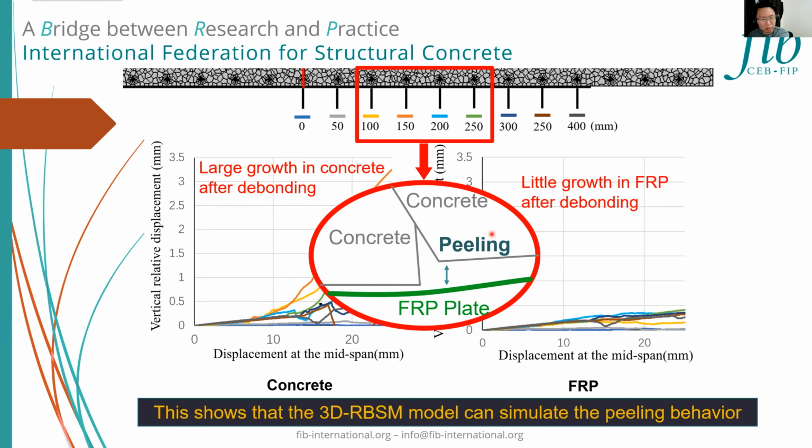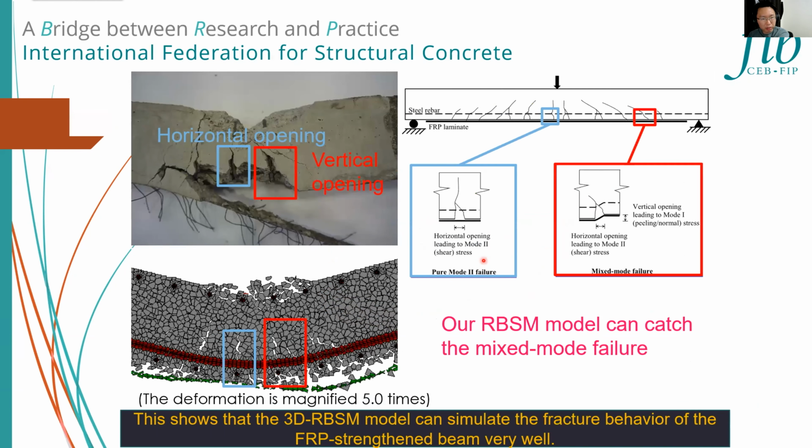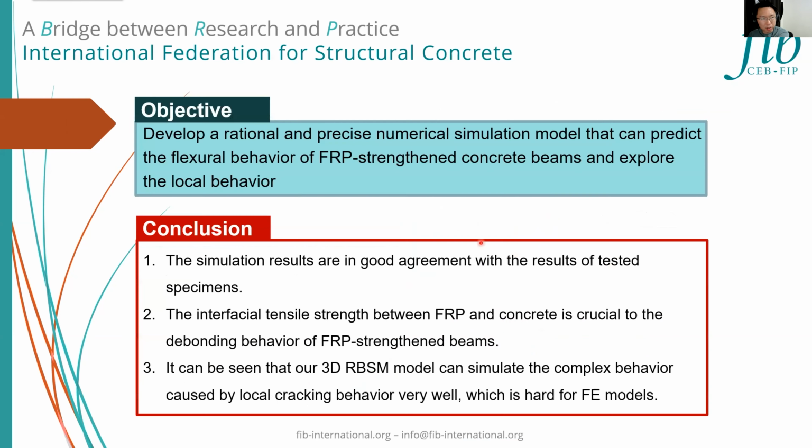This is our advantage. The result of successfully simulating the local behavior, the microscopic behavior of the beam can be simulated. From the crack pattern and the local vertical relative displacement curve, our RBS model can successfully catch the mixed mode failure. And this is my conclusion.